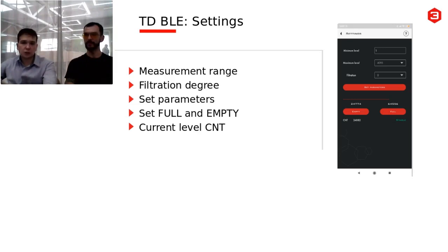If the current level is way above the full value that you had previously installed, in this case, you probably got a short circuit. This happens when some alien materials, alien liquids get between the tubes, like water, for example, or some alien objects like little pieces of metal. They actually connect the tubes between themselves, and this causes this short circuit.